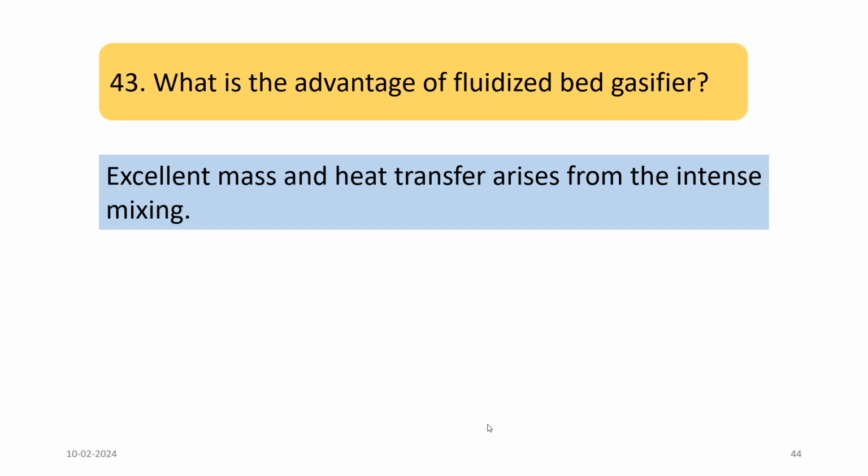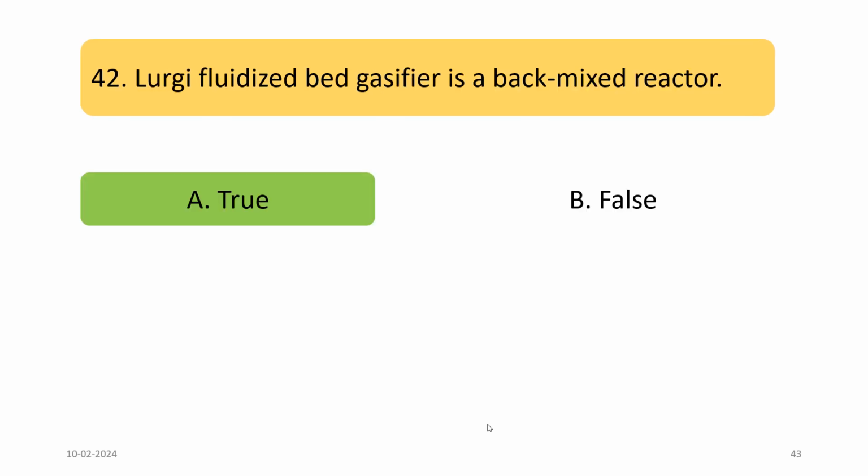The answer is excellent mass and heat transfer arising from the intense mixing. As we just saw, the fluidized bed gasifier is a back mixed reactor.